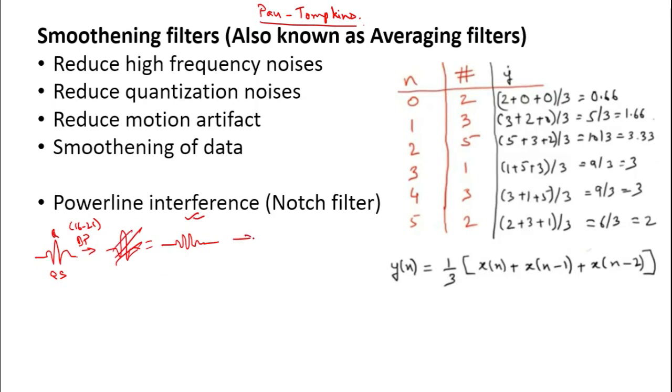Next, what happens is that we do squaring. So what happens? Across this baseline, there are bipolar signals. So then it becomes unipolar signal. Something like that. Okay. Now the smoothing filter is applied, and while it is being applied, it becomes a hump.